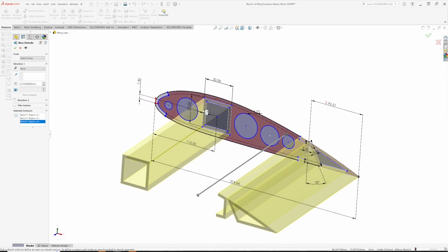Chances are the first time you do it, your sketch will not be watertight. There'll be bits where you've got the wrong line types, or the points don't join up. So it can be a little bit frustrating to start off with. If your sketch gets into a bit of a mess, it's quite often quicker to delete it and start again. Trying to find tiny bits where you haven't joined up is difficult. You may have to do it a couple of times, but when you've done it right, these things should extrude out properly.